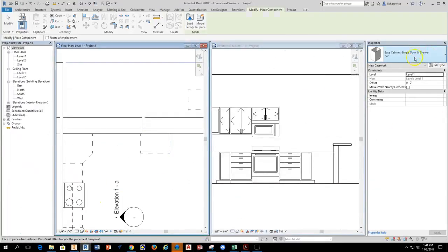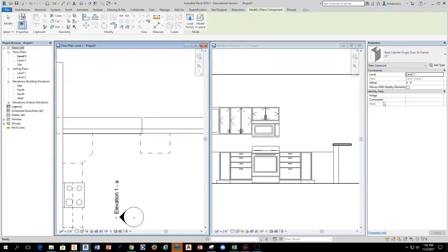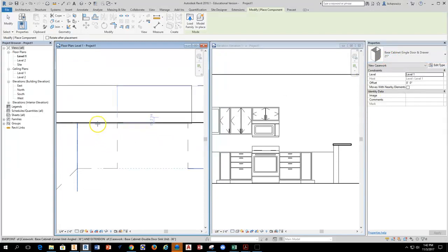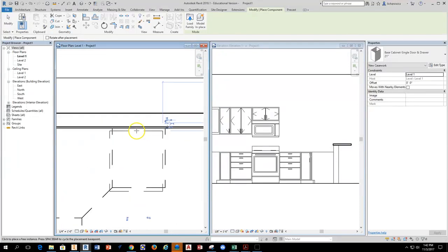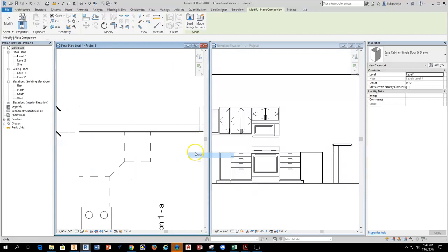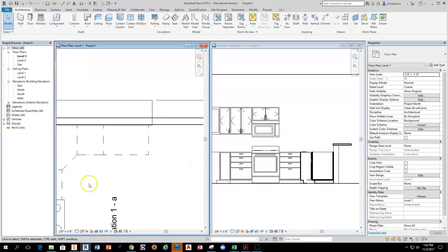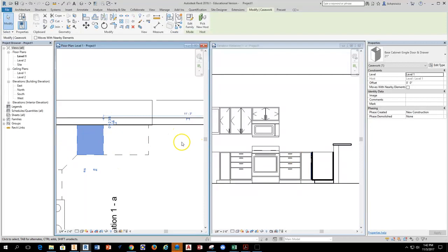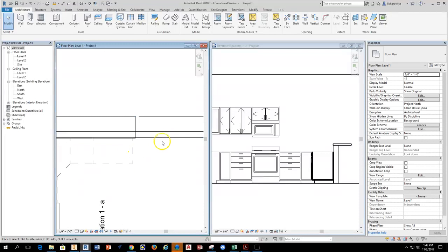Back in here to Revit. So there's a 21-inch. Grab this, and when this actually sits itself next to the drop, that right there against the wall. That sits next to the corner cabinet, and then I can take and move my base cabinet. Slides over into position here. And then I'm going to go ahead and drop, actually I can just copy this. It's the same cabinet. Actually, no, that's where the dishwasher is going to sit. So basically just need to give space for the dishwasher and then the end of the wall. So the blank panel would end up out here in this area so the dishwasher could slide in.